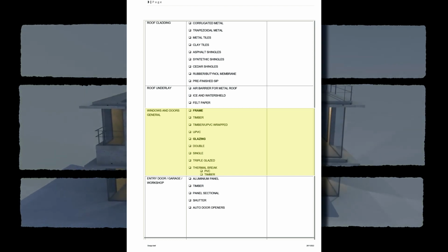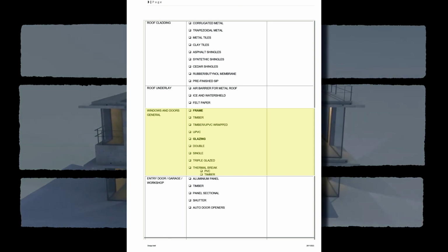As for the glazing, the climate, location, or jurisdiction of the project may affect the type of glazing you will need to specify. Single glazed or sealed double or triple glazed are options listed here. You will also want to note if the client wishes to introduce gas into the sealed window units. Options include low-E and argon gas.